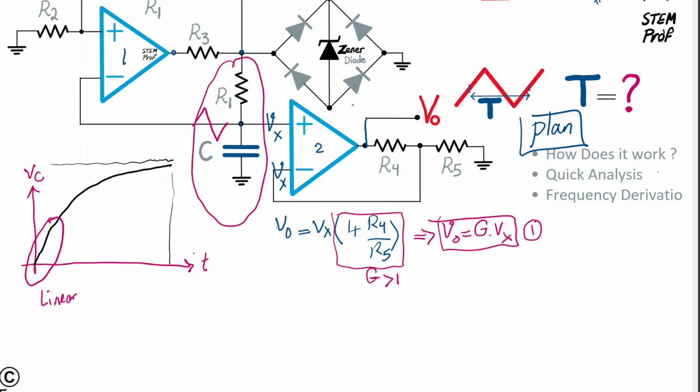And in the same manner, when the cap is discharging like this, then we can just stick with the linear region of discharging at the beginning of the exponential drop of the capacitor voltage so that we again mimic the downturn, or drop, in the triangular waveform.